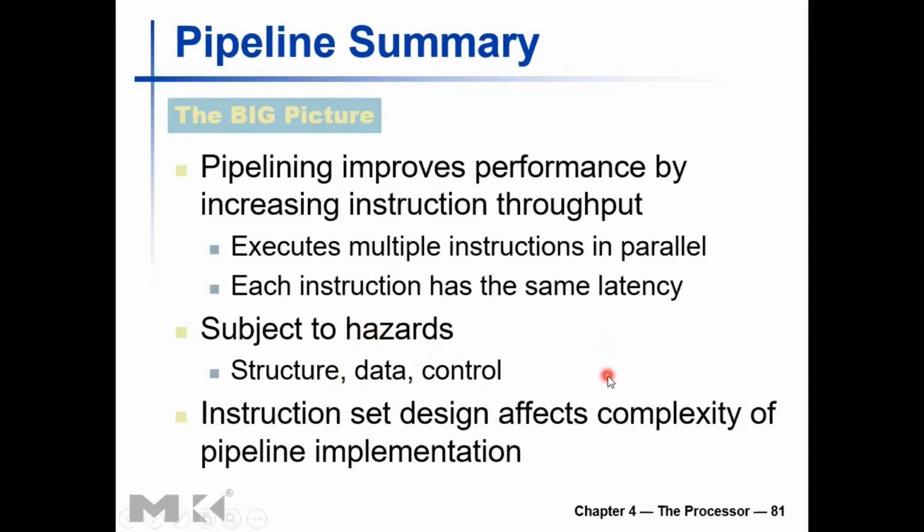And then one other thing to keep in mind is the instruction set itself, the ISA, affects the complexity of the pipeline implementation. And like we discussed, the MIPS ISA was designed to be implemented as a pipeline, not as a single cycle or a non-pipeline multi-cycle implementation.